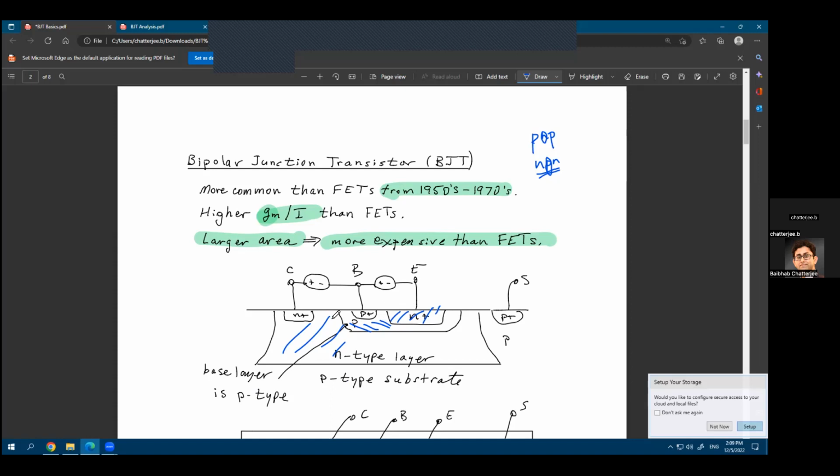Can the electrons or holes traverse from the source to the drain, or in this case, between the emitter and the collector? If my base is extremely long, let's say a kilometer-long semiconductor, it cannot, right? So it will not have enough inertia. Again, inertia is an analogy here, but you can think of it in those terms. So the base has to be very small for the carriers to start from the emitter, cross the base region, and be available at the collector.